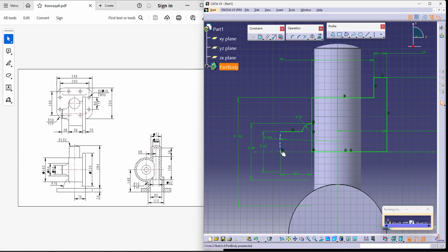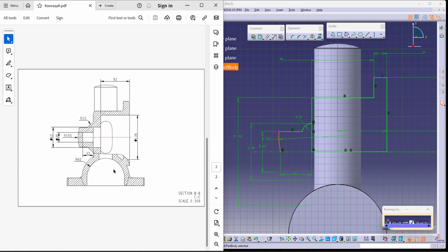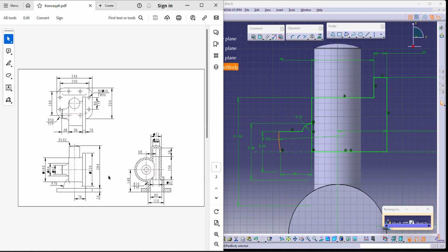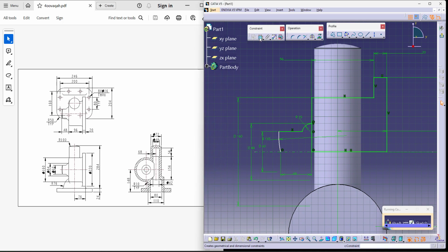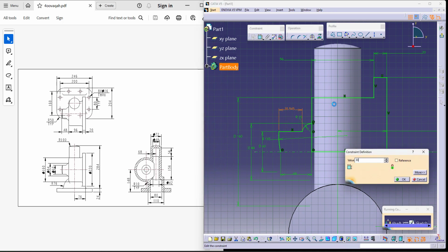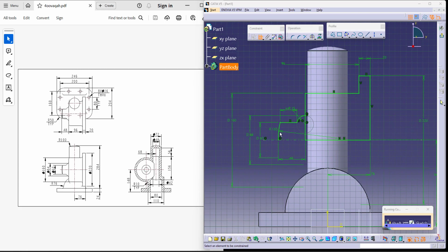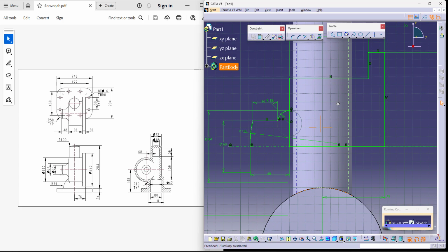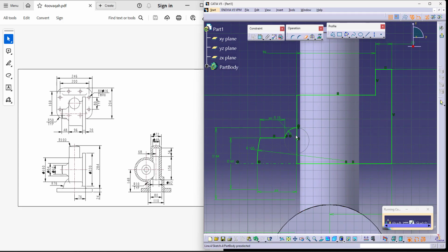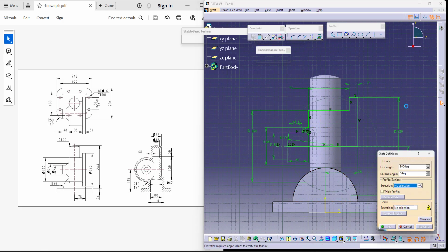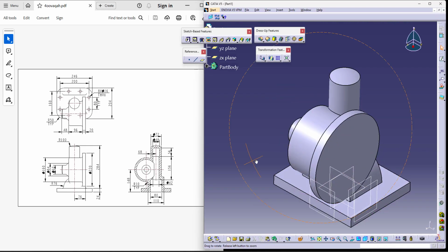These are the dimensions. Now the overall length is 48, which is already given. Okay, assuming the length of this is around 30. Okay, so after this, let's try to close the model and then try to create the shaft. So before doing that, let me try to delete the unnecessary lines and then extend whatever is required. Then we can proceed further. Now, once I exit, you will be able to see that it creates a shaft.